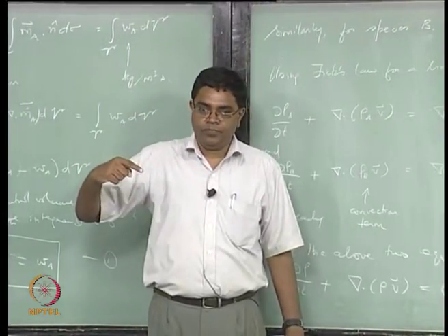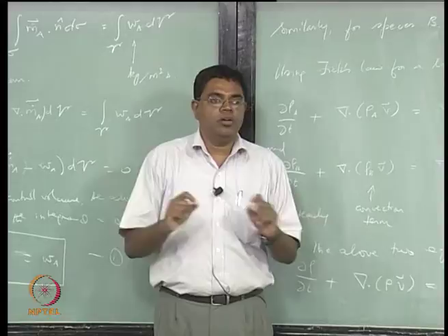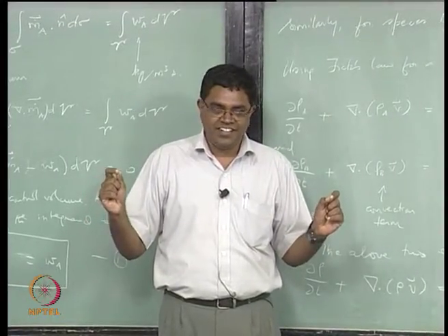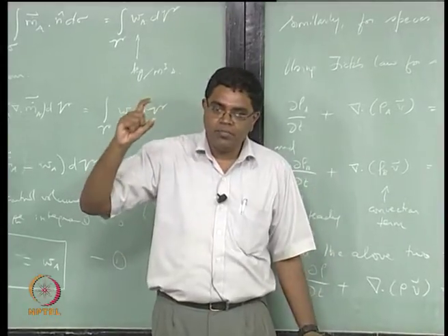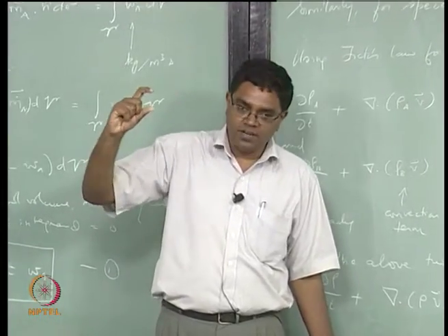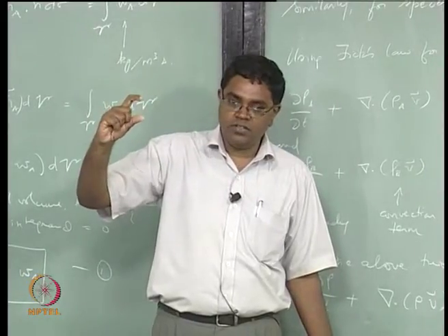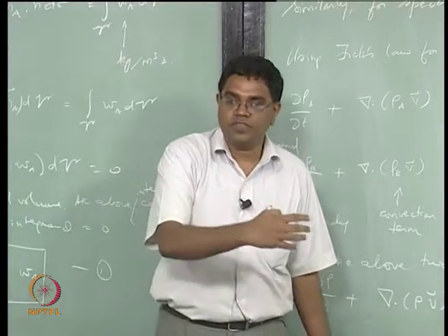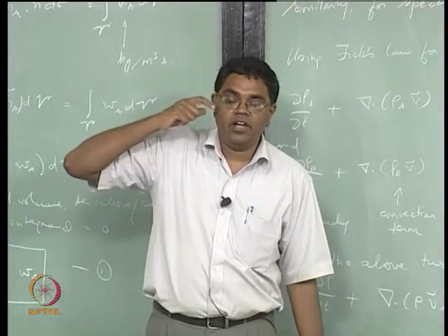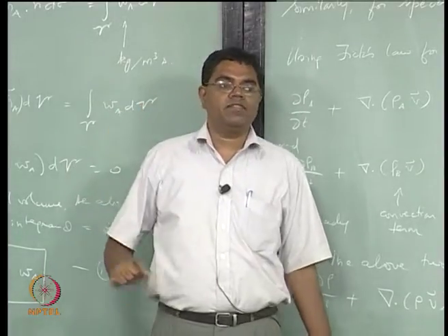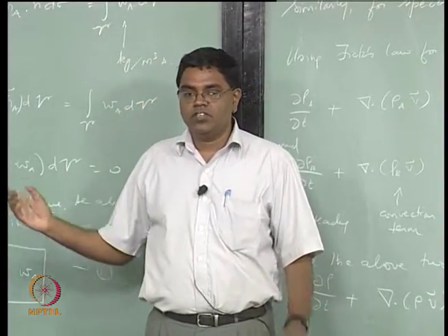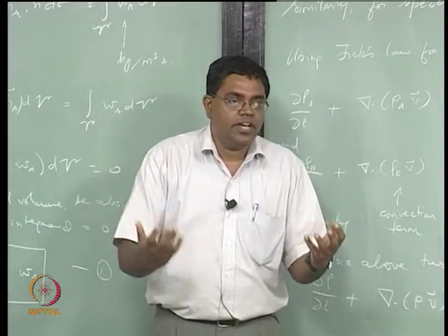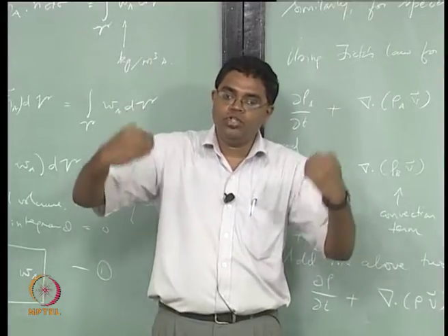This is how Fick's laws were formulated, but we can find that the first law that we started using cannot be derived from a continuum point of view. It is stated as a law. We said we needed that law because we wanted a connection between the diffusion mass flux, that is what else the species is doing other than going with the rest of the mixture. We needed an expression for that in terms of a primary variable, namely the concentration. So that was the constitutive relationship that Fick's first law provided to us, and it can be obtained only if you get down to the molecular level.